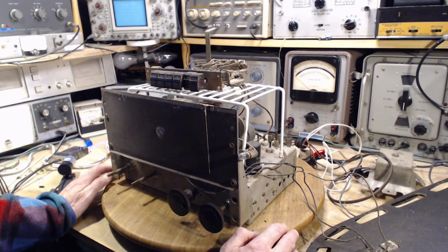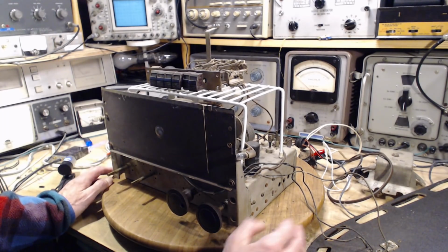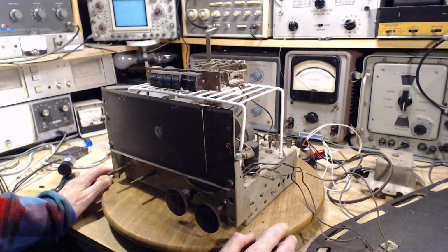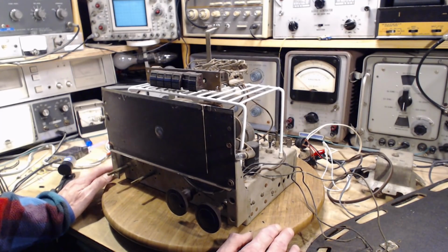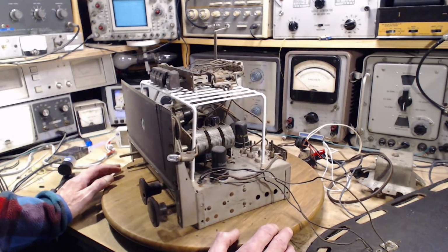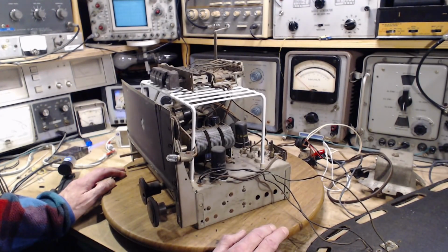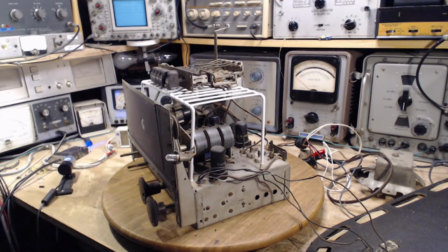Okay, so I think I got the order figured out now. Leave everything as it is. Get it operating from the signal generator. Get out the voltmeter, read the pin voltages on the audio tubes. Maybe on the other tubes too while I'm doing it. And see where all that leaves us. That's the first step. We'll have to kind of do it and see what the result is before making a decision around what to do after that.